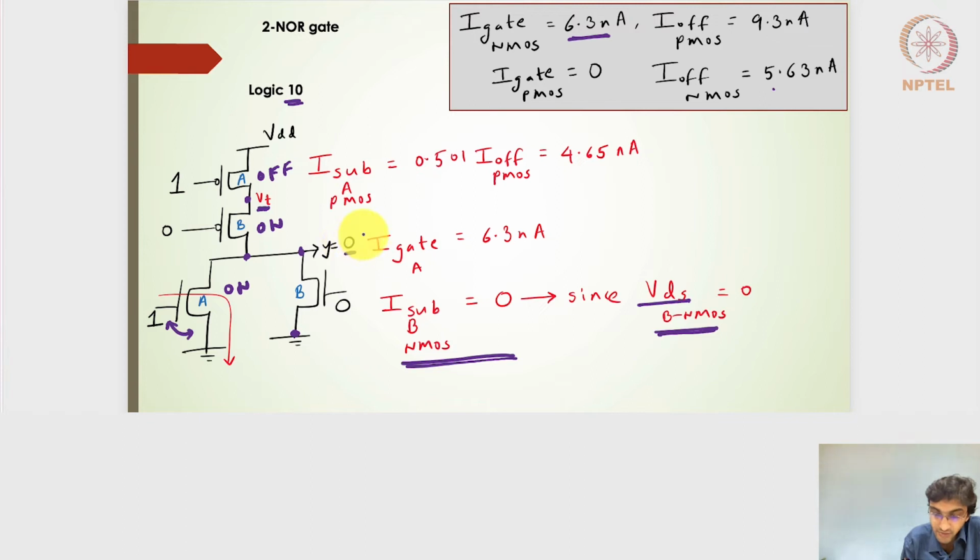So if I have a Y equal to VDD, it is then discharged toward 0. So this particular node will have some higher node voltage, and while it is discharging through the pull down side, it will limit itself to VT. So it cannot reduce further than the VT value. Otherwise, this channel will not be there. So it will be limited to VT, and that's how the PMOS pass transistor works. So if it is 0 on this side, it is going to limit the voltage to VT on the other side. And if I have a VT voltage here, then I should be able to find out